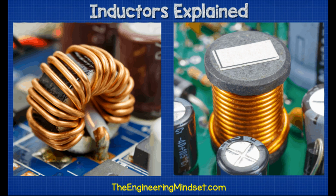Pulse transformers. Application. Pulse transformers are used in digital circuits to transfer fast pulse signals between different parts of a circuit. They are designed to handle high-speed signals while isolating the transmitting and receiving circuits. Example: pulse transformers are used in Ethernet transceivers and communication devices to transfer data signals between circuits with high-speed accuracy.